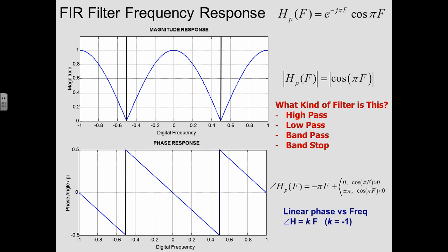What this straight line phase plot is telling us is that this low pass filter, as crummy as it is as a low pass filter, has one nice property: it doesn't realign signals of different frequencies. It doesn't distort their phase when I put a signal through this filter.